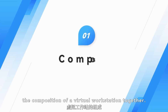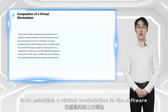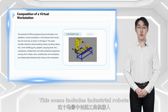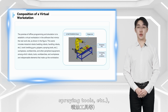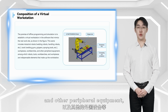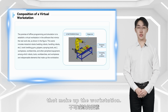First, let's understand the composition of a virtual workstation together. The premise of offline programming and simulation is to establish a virtual workstation in the software that mimics the real worksite, as shown in the figure. This scene includes industrial robots, welding robots, handling robots, etc., tools, welding guns, grippers, spraying tools, etc., workpieces, workbenches, and other peripheral equipment, among which robots, tools, workbenches, and workpieces are indispensable elements that make up the workstation.